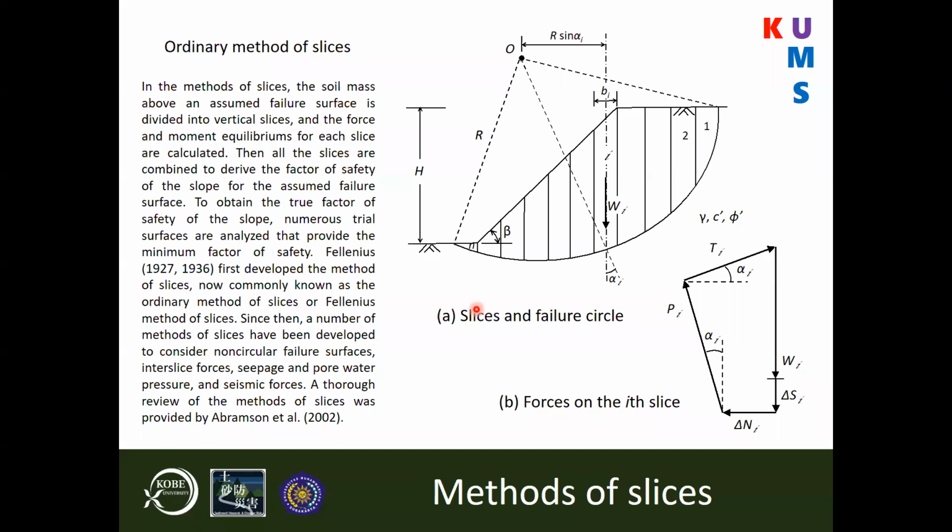And say, well, if one of the slices is weak, that's enough for that whole mass actually to go and start moving. So I think that you should go with the second approach. That's why I mentioned it here in the text. I think it's much safer to consider the approach with the weakest slice rather than taking the addition of all of them. And that's the kind of method that we call method of slice. So in conclusion, we are 10 minutes earlier.